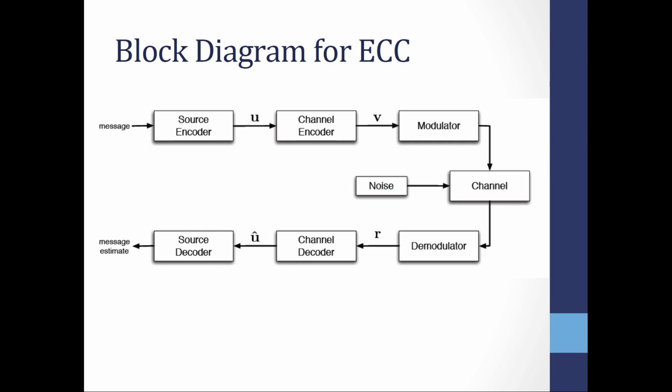After the source encoder, you use the channel encoder. The channel encoder adds redundant bits to your message data, which we call parity bits, and they are responsible for protecting your data from the noisy channel, so that you can receive all your data bits successfully and conduct your transmission in a reliable manner.